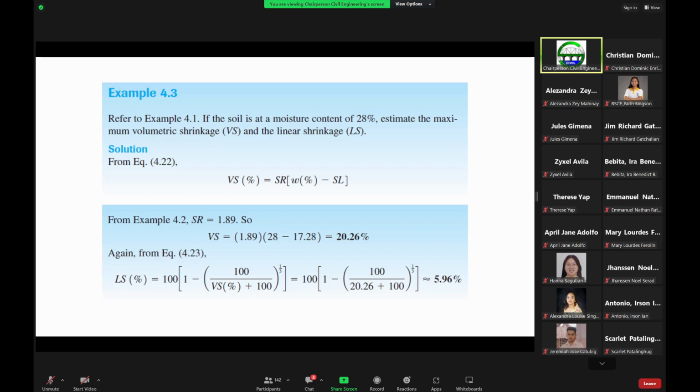So if you have 30 meters depth, for example, and I specify to have it tested in the lab every 1.5 meters of soil sample extraction, then in a 30-meter depth of geotechnical drilling work, you will expect 20 soil samples in one borehole.